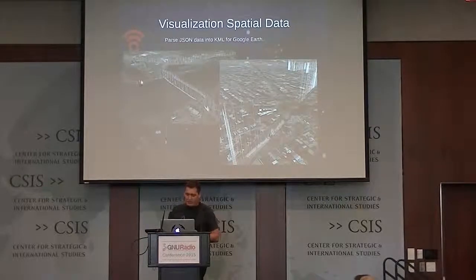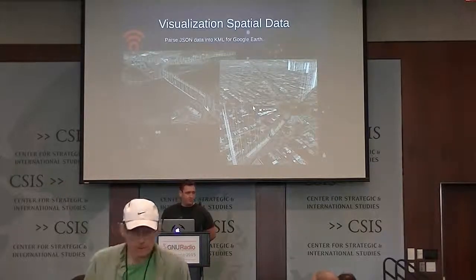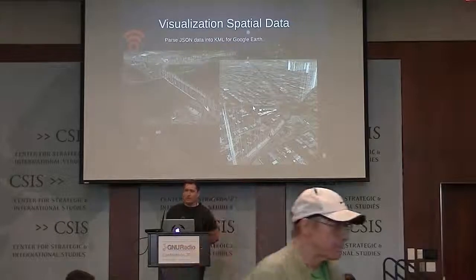Like as you go up and over this bridge, you saw that signal strength climbed, and you have this great clear line of sight. And so signal strength is very high, and then once you go back down the ramp over here, you're going to start losing your line of sight again. Same thing here. This is actually driving right under Dupont Circle. You go through this tunnel here, and you can see the RSSI drops, and actually some of these are because of GPS loss, not because of signal strength loss. But regardless, you can see the signal strength dipping as you go in. So it's cool to be able to visualize these sorts of radio effects.